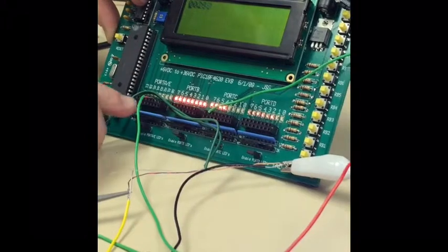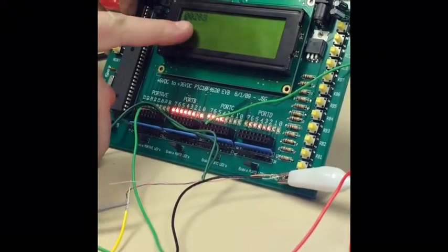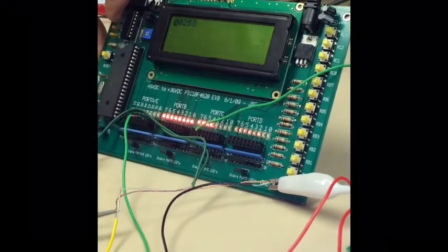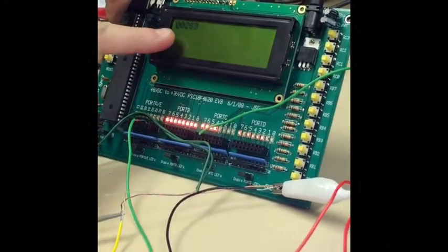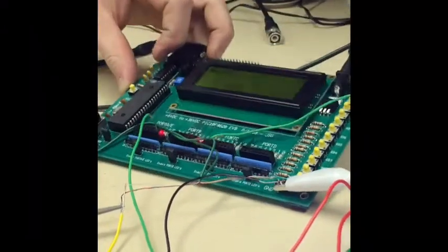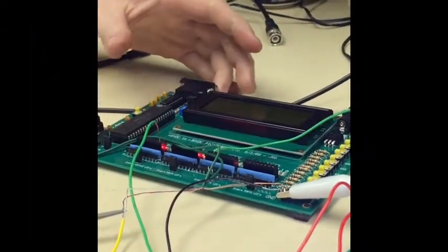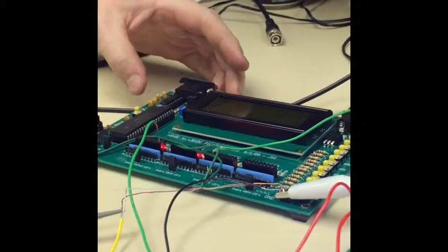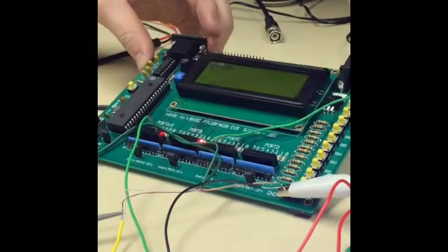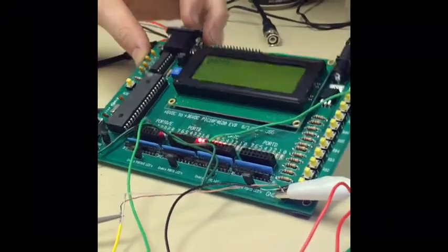And this takes a reading of the voltage on that pin, and it equates it to a number. 0 volts in would be the number 0, and 5 volts in would be the number 1023. So we have 1023 degrees of resolution. For this project, we have a 1 volt wave in, maybe 1.5 when we play music and there's a spike. So we predicted the maximum voltage in to be about 3 volts. So the highest reading we should get on this is about 600.